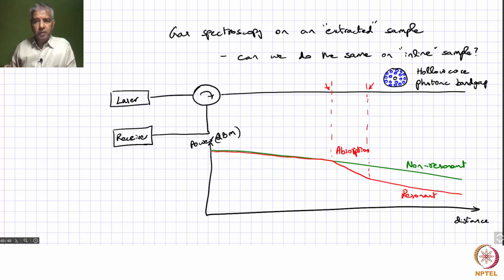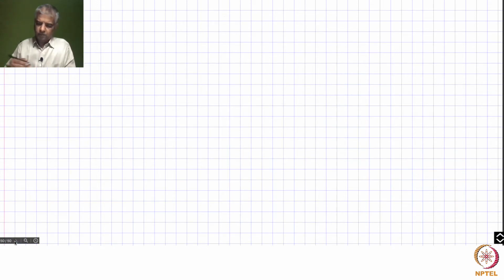So far, we have been looking at amplitude modulated sensors. I think we have covered enough about that. There are, of course, like I said, several other examples of amplitude modulated sensors, but you will typically have the same issues. You are looking at changes in amplitude. The challenges you typically face are background changes, and you also have noise as a very important aspect of your detection.